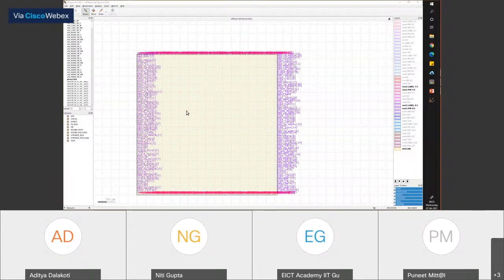If I run flow instead of this, if I would have run floorplan, then it would have done all of this together in one command itself. So all these commands are created to run in the tool environment, and they are supposed to run a set of scripts. After this course, as a future exploration, you should try to observe and understand this OpenLane environment more and more: where each of these commands, what scripts they are sourcing, and so on.